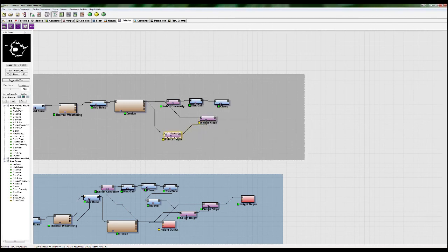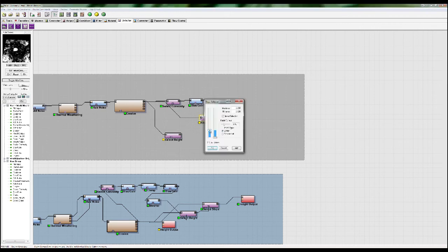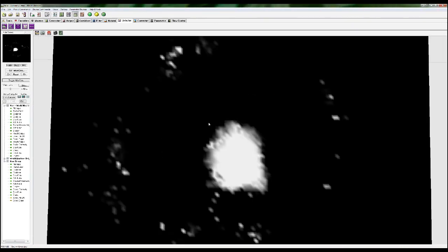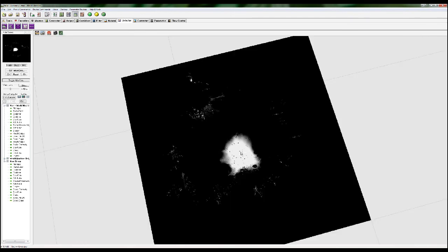So what we've done is we've selected the white areas on our terrain, which are at a certain altitude. We're selecting a certain height, so we've got that ring around there. The reason we want that is we want this middle circle, and then we're plugging this into the mask of a select slope. So if I just disable that, you can see I've selected slopes which are flatter, so I'm getting rid of these steep areas which come up to the volcano's crater. So when I go to mask that out, select that, and we've got a good nice area in the middle here.